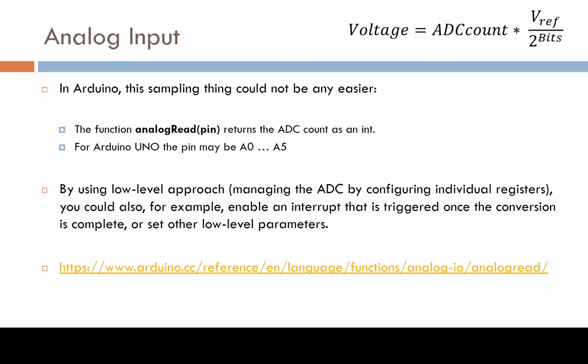Sampling is done when you are doing A to D conversion, and also when you just pick values from data. If you're not using every single data point, but you pick just every 10th or so, that's also sampling. And filtering should be used.